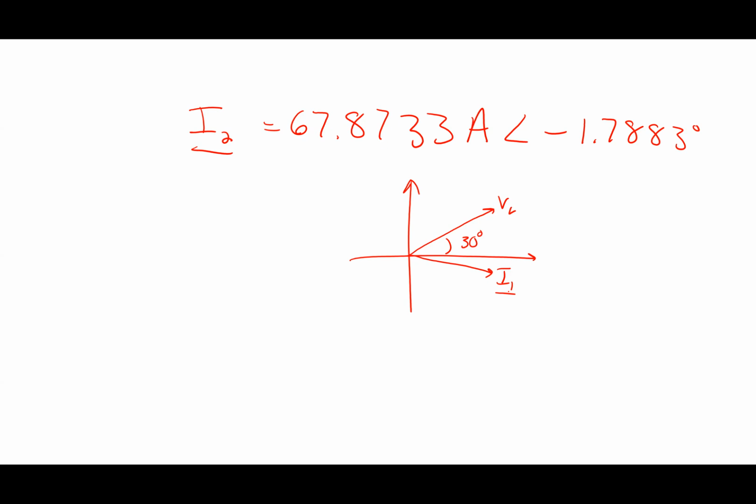If his power factor was 0, what would the angle between the voltage and the current be? It'd be a 90-degree shift between them. Which would basically mean that the load was doing no real work. Your house would just be an inductor, which would be useless. It would be a very dark house. It'd be very cold, but you'd be storing a lot of energy. And when you said that the power factor was 0.85, that's pretty low for a house. Ideally, you'd want it to be 1.